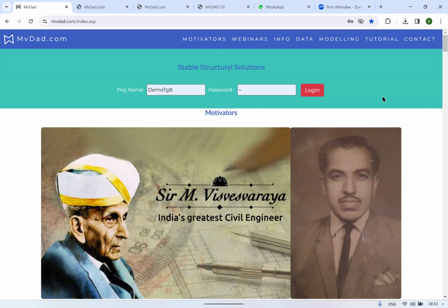Okay, sir. The similar project, what we are doing, we are providing for number of colleges. Our zone is 2, that means 0.1 seismic factor. Even the same building, if it comes in zone 4 or zone 5, then seismic factor is 0.36 or 0.24. Then how does it behave in that particular location?